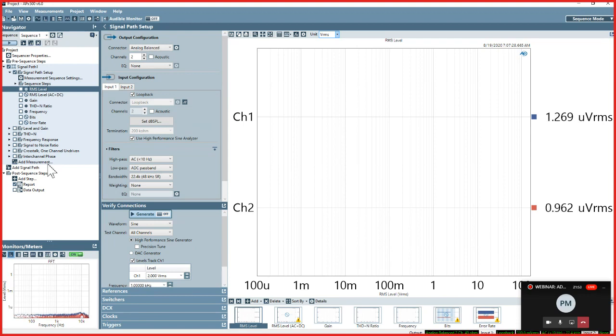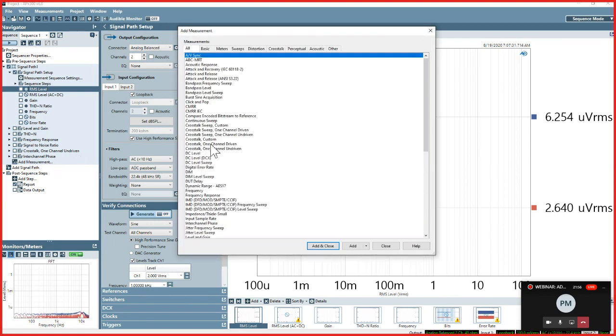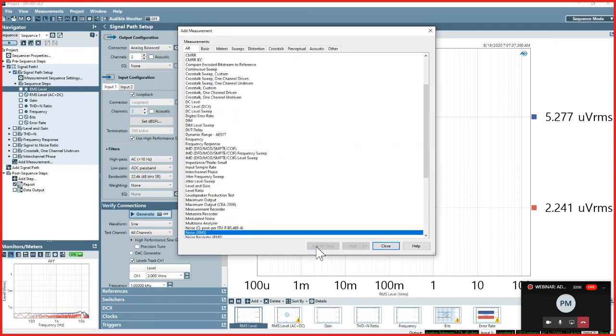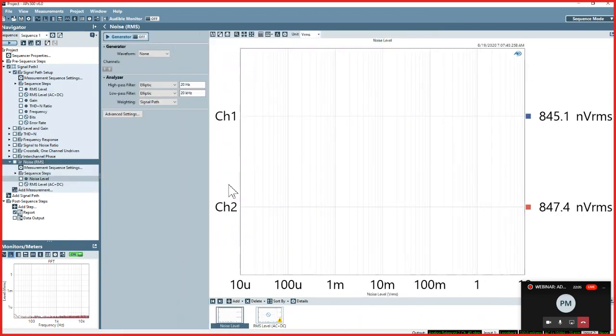So now we're looking at the analyzer's residual self noise. Again, if we wanted to measure the noise of a converter, we would reach the threshold of the analyzer at something a little under a microvolt. Now, another figure that may come up is if we want to test a device's frequency response all the way across its passband. So let's take a look at that for a moment.